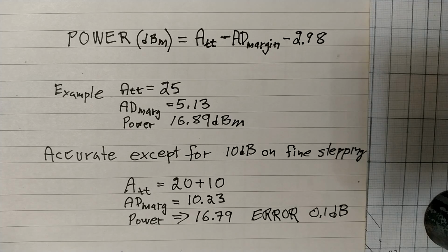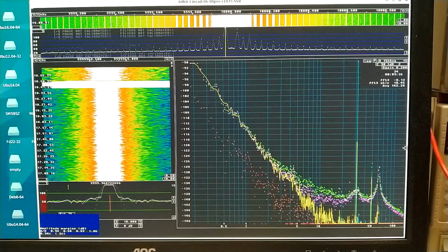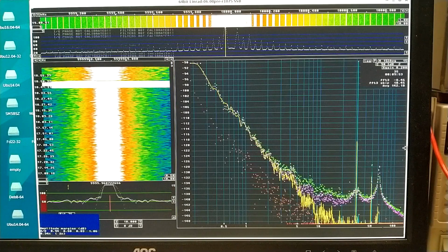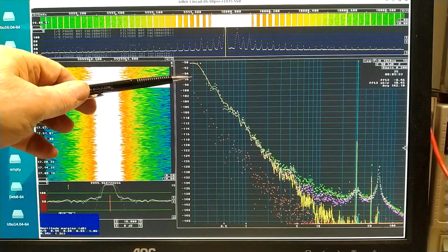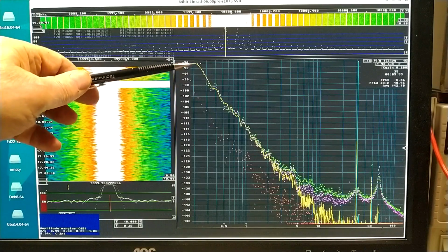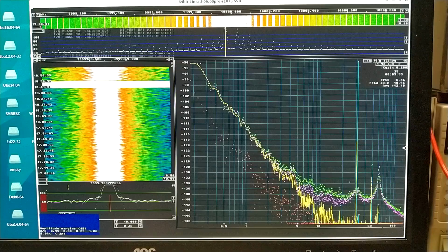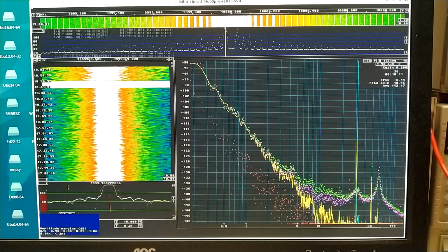I have adjusted the coupling capacitor to the crystal to get an output power 2 decibels higher than before. That means 18.8 dBm. Already after 10 minutes I can see that more power was a bad idea. At 0.2 Hz I had about 95 before. That's here. And I have lost probably 6 decibels at 0.2 Hz. On the other hand, of course, at wide separations it is very likely different.